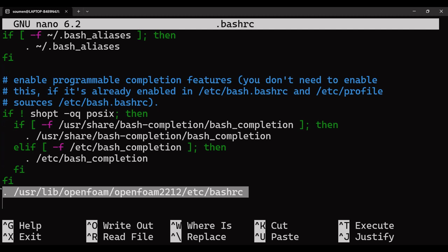So this is the best way of doing it at once so that you don't have to do it another time. If you don't have this command written, you have to do it every time. Instead of this dot, you could basically set an alias of some keyword to do this. Okay. So is it clear why I am able to use OpenFOAM? Because it is already sourcing the bashrc file whenever we turn on the operating system.